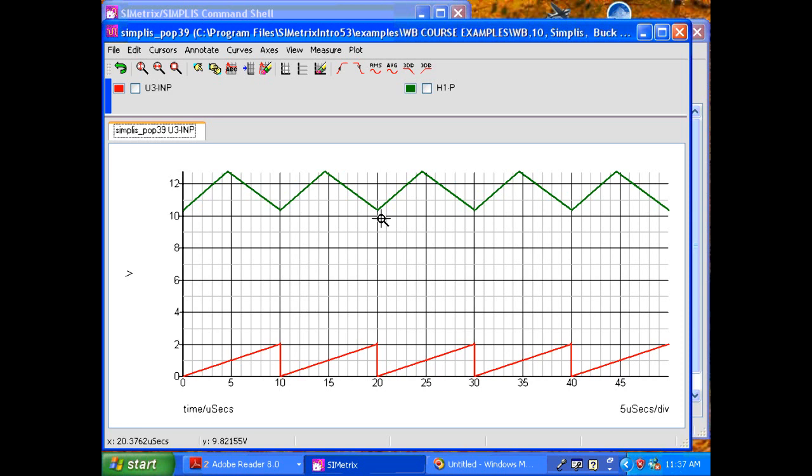For the highest line susceptibility, you want the slope of the sawtooth to be 1/2 the slope of the current voltage coming back. There's a voltage proportional to the current when we mix them. This one wants to be 1/2 the slope of this waveform. It's as simple as that. They're actually there at this point. We can measure that if we want to. We won't take the time.